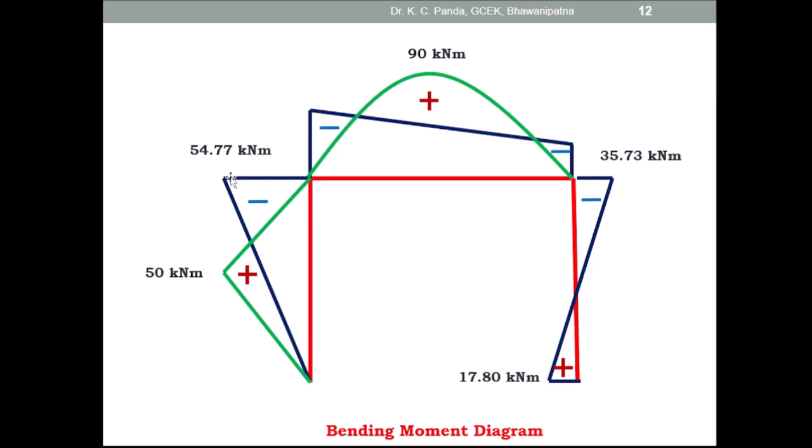Similarly here, you know this ordinate, and you also have to find this ordinate by taking two similar triangles. After knowing this ordinate, from the total ordinate you deduct this portion, so that you get the positive moment here. So this is the complete final bending moment diagram of the non-sway portal frame.